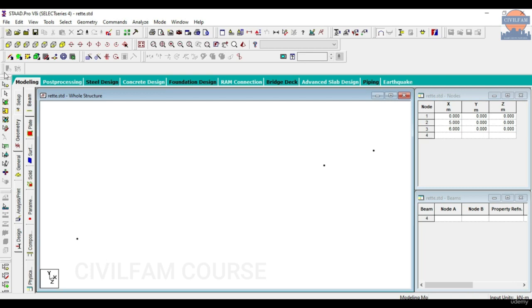This is basically my, let me take my node cursor on, select this. This is basically my 0 comma 0 comma 0. That's my point of origin. So all the time what was happening was I was always going on in the x direction. To draw the portal frames, I have to go even in the y direction.